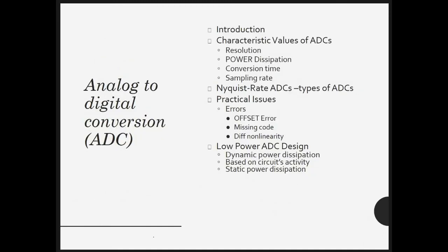The next important topic is analog to digital conversion. Analog to digital conversion is a system that converts a continuously variable signal, without altering its essential contents, into a multi-level signal. Analog to digital converter inputs consist of a voltage that varies among a theoretically infinite number of values. For example, a sine wave, the waveform representing human speech, and signals from a conventional television camera. The output of an ADC, in contrast, has defined levels or states. The simplest digital signal has only two states, in binary form zeros and ones.